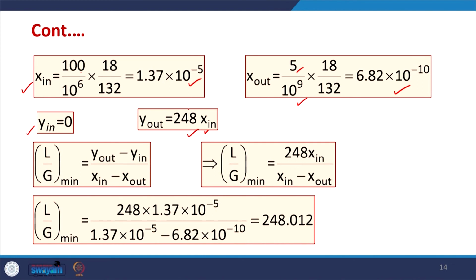Now, the mole fraction in the liquid phase is known and the G value is also known. So, V out, this is the maximum V out possible, but it will never be the same, it will be much lesser than that. At this condition the height of the tower will become enormous. So, it is not possible.